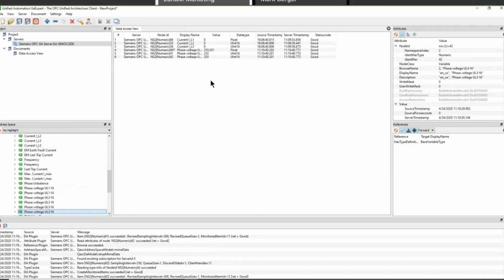And I'm going to turn it on right now. Okay, current is running. Please note the two differences. This one here is the percentage of the full load amps of the motor, and then up here is the actual current draw. So my demo has 0.5 amps, half an amp, for its full load amps. So I can have it in percentage or I can show it in raw value.